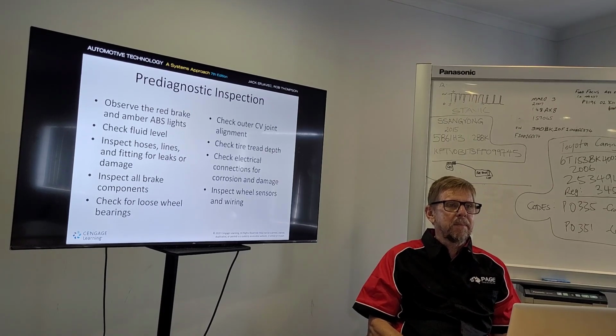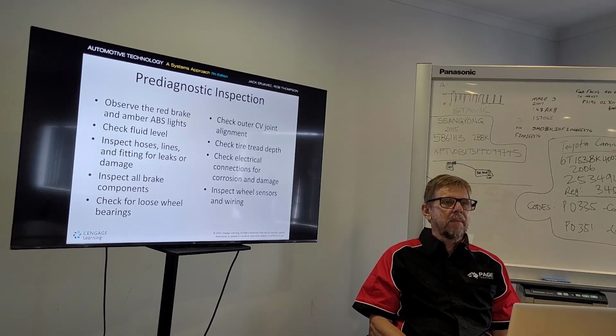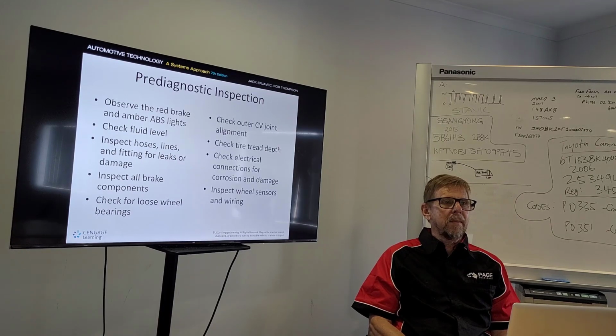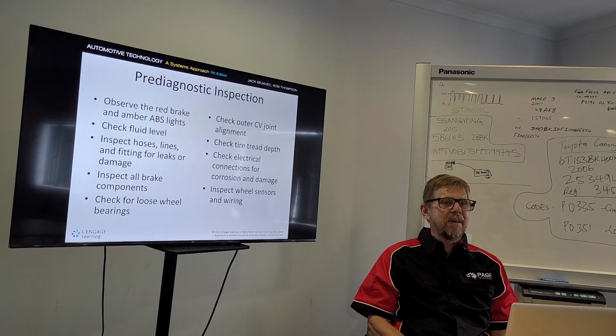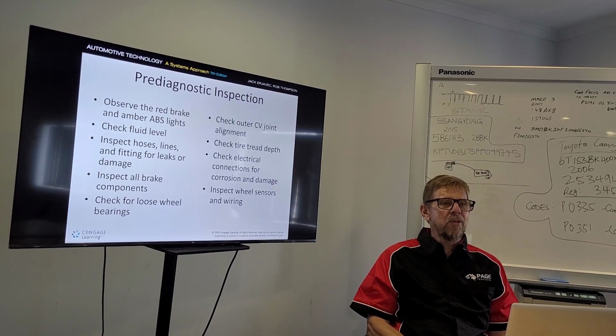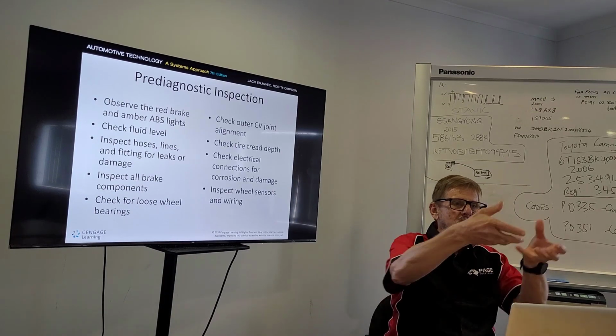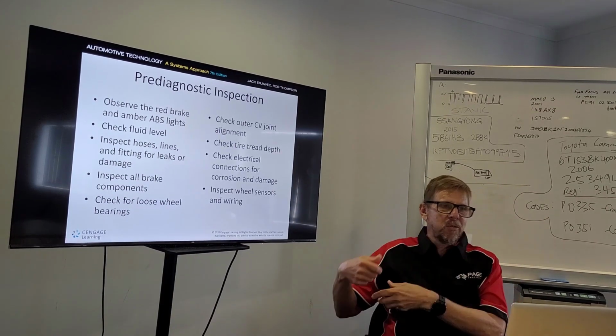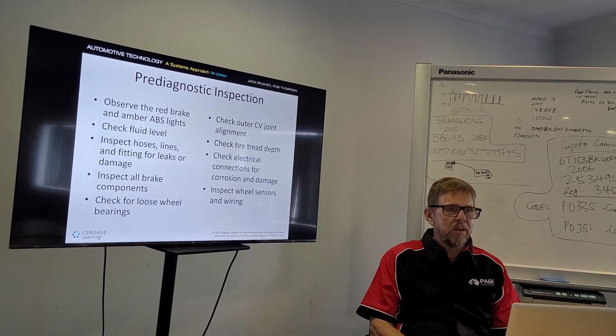One customer came in the other day and the customer is saying, oh, I think my alternator is making noise. I said, no, your AC compressor is making noise. So that's a very good tool. Sometimes noises do transfer. For example, a diff noise can transfer up the tail shaft. You think it's coming from the transmission, it's really the diff. So you can get caught, but it is a good tool.